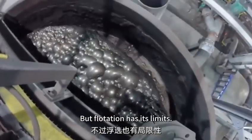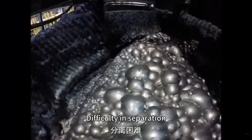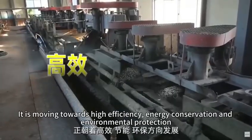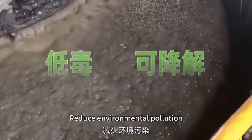But flotation has its limits. For example, very fine particles, less than 10 microns, or ores with similar surface properties, are difficult to separate. At this point, it needs to be combined with other methods. Modern flotation technology is moving towards high efficiency, energy conservation, and more attention to environmental protection, towards low toxicity and reducing environmental pollution.